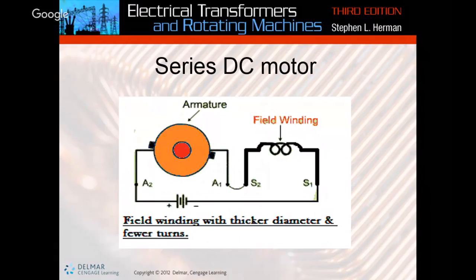But when we're talking in parallel, the shunt wound, the field current doesn't really have to do anything except produce a magnetic field. The field in this one also has to maintain the wire size so that once this huge amount of current gets loaded on it, it doesn't just blow out. If we had one of those little tiny wires with a couple of wraps on it and put it in line with the armature current, that thing would explode. That's a huge amount of current going through there.